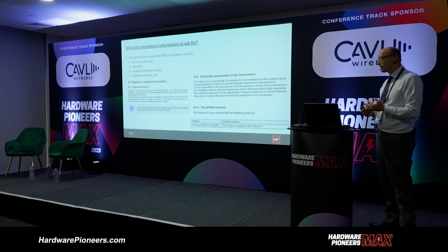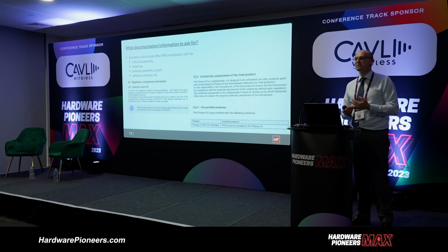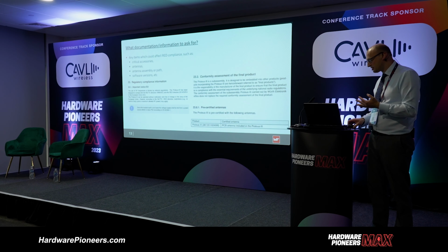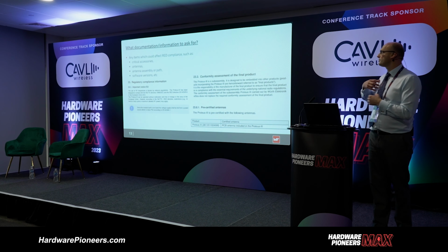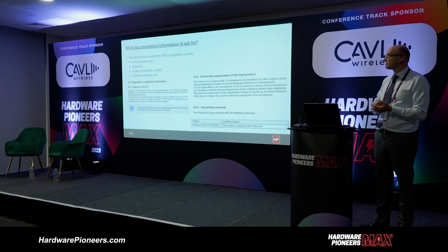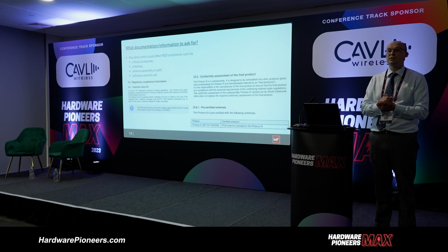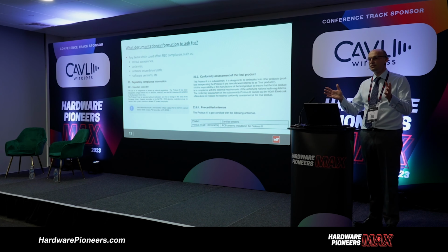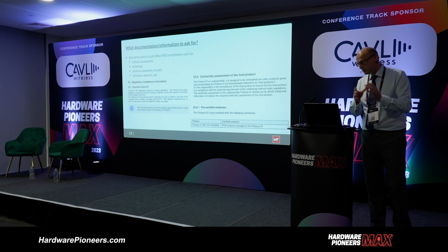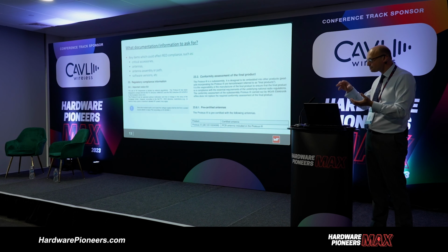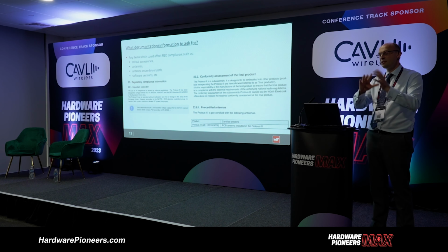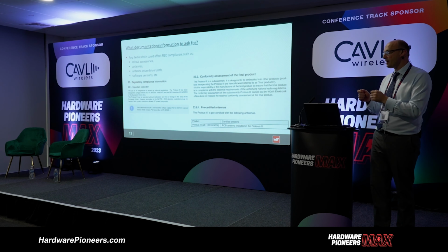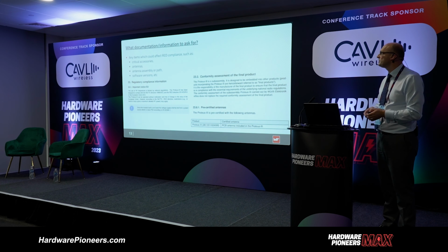Antennas. We do get questions about, is it possible I can change my antenna with regard to my module? If the module has been tested and certified, from our perspective, our declaration of conformity should be clear, as well as our instruction manual, as to what antenna has been used with that particular RF module. As soon as you change that antenna or the antenna path, in effect, you have a new product. You've invalidated any certification or pre-testing that's been done on that module, and you would then have to re-evaluate the whole radio equipment. So yes, it is possible to change antennas, but you've got to be aware of the consequences and the ramifications of that approval.